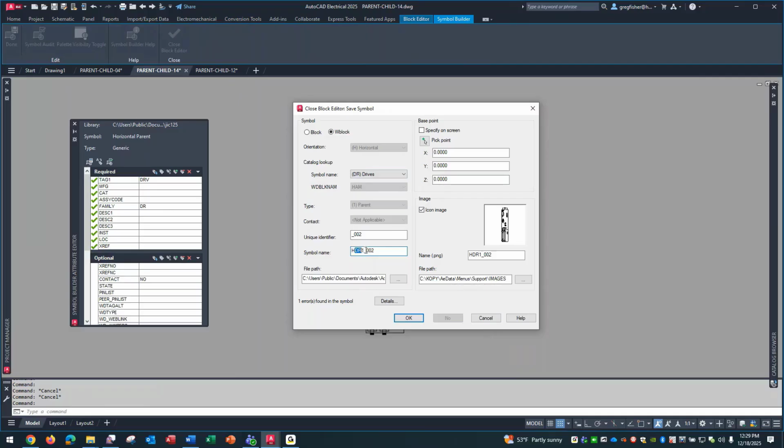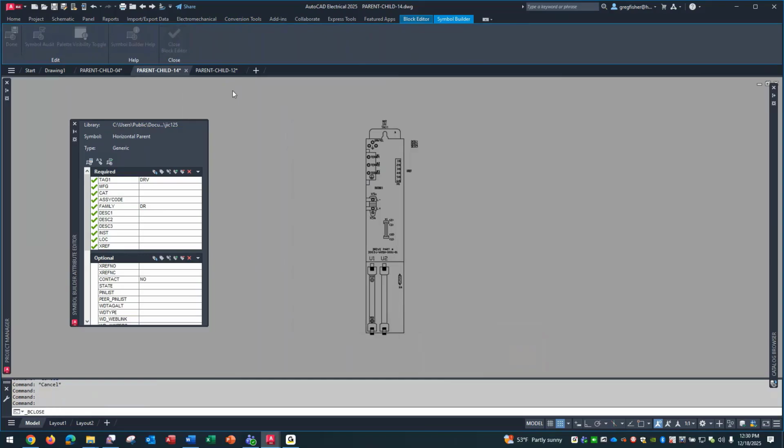And then I just put my own spin on the symbol name, like, as you know, or I'm assuming some of you know, when you create a custom symbol, you can put your own spin on the symbol name, and that's where I would get into the detail of the symbol name. But again, the reason why I'm bringing this up is when you go generic on a symbol, you still want to make sure that you hit the catalog lookup in the last dialog box of the symbol so you can apply the proper table, not just leave it as DV. So let me get out of that.